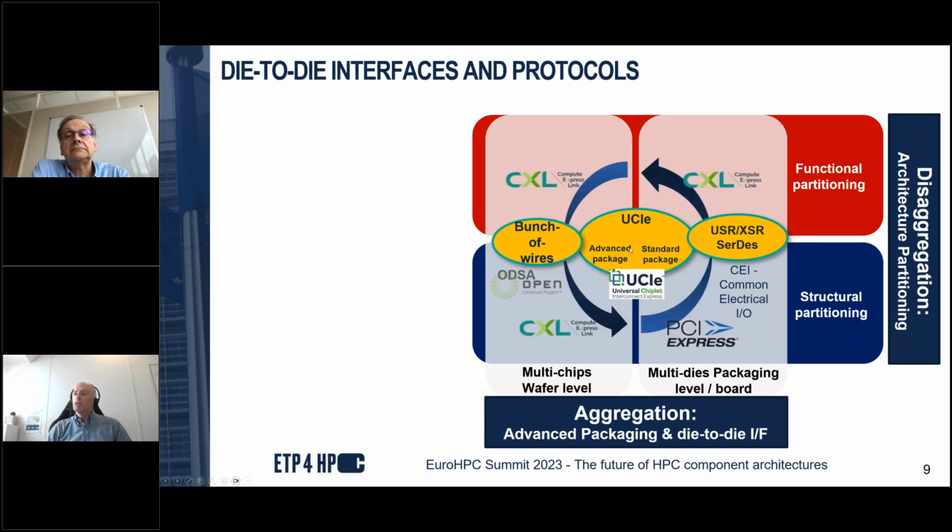And then this will have to link with the socket to socket, or socket to interconnect, or socket to memory interfaces. CXL offers a real promise here in that it can be a universal interconnect to memory, to other compute elements, whether it's between CPUs or CPUs to accelerators, and to I/O. Today, not all of those are fully baked, but those are the three targets for CXL.